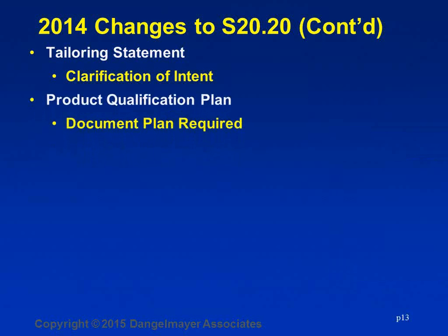In the 2007 version, there was a note in the table that talked about product qualification. In other words, all of the items that you purchase to control static and deal with in your plan, you've got to qualify somehow. There's now an entire section of 20.20 related to that. It's a required element now. And this is one of the items I think really beefs up the standard in enforcing good quality products are purchased for controlling your ESD program.